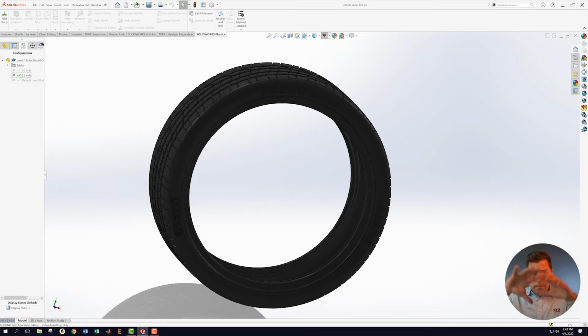So for the rim, the outside part with the largest diameter, I'm going to use surface modeling. I'm going to get the surfaces off the tire that need to match. And then I'm going to use a Revolve to get the inside part of the rim that's not matching with the tire. And then I'm going to turn that into a solid. And then I'm going to pause and check to see if this is working.